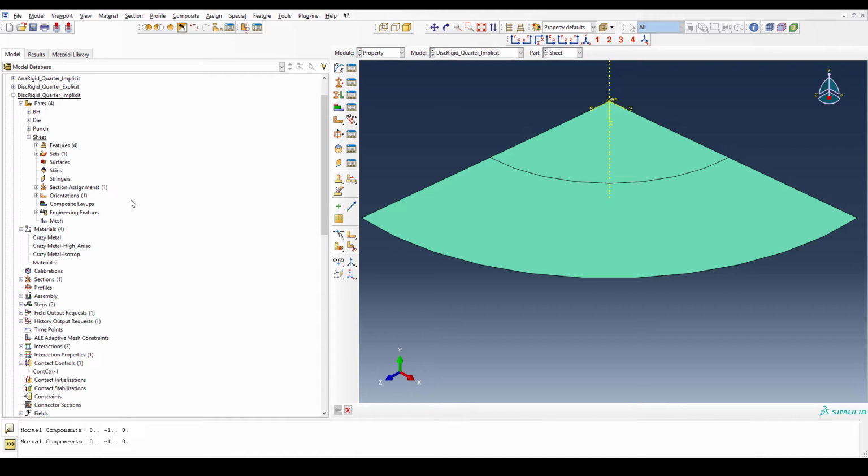Alright, so that's very important, because otherwise your anisotropic material model doesn't know which directions you mean when you specify your anisotropy values for your Hill condition. Which are, as I've shown in the other video, based on your Lankford parameters.